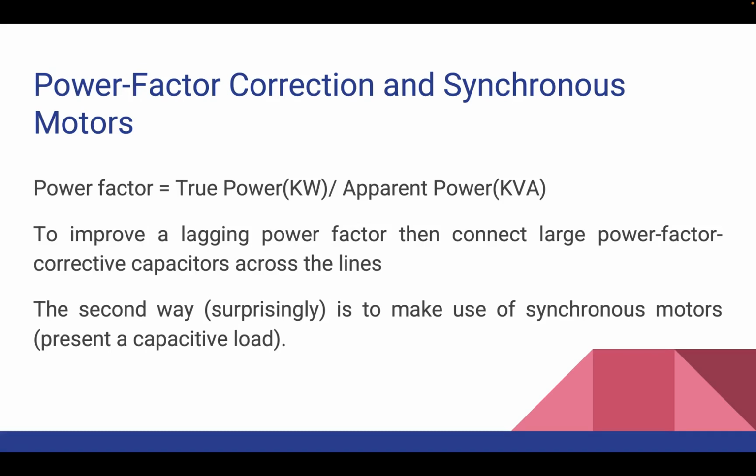So we learned that a synchronous motor can be used as a synchronous condenser, which provides the function of power factor correction, because if we have a power factor of 1, then we can have the maximum power transferred from one point to another.